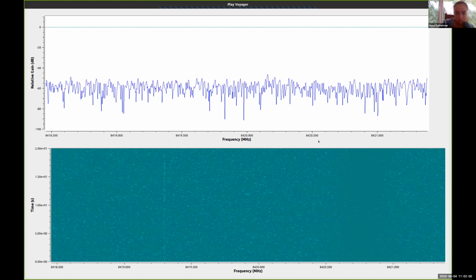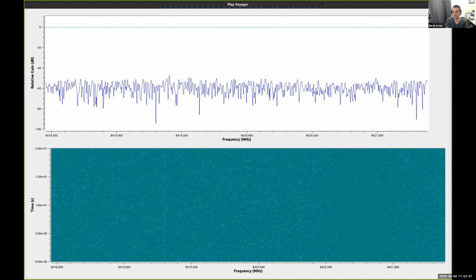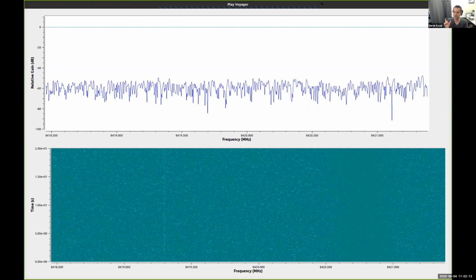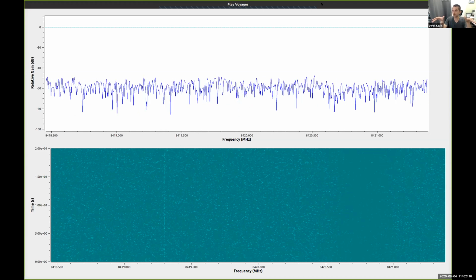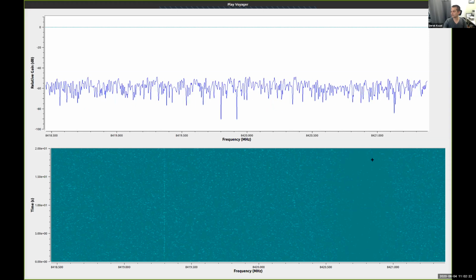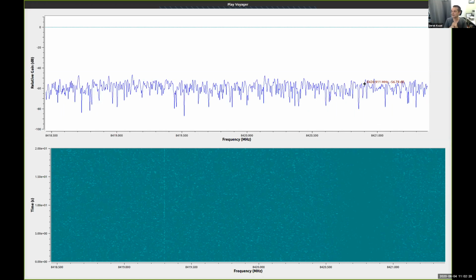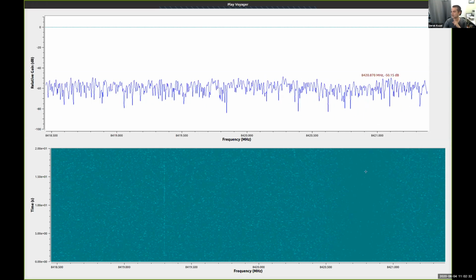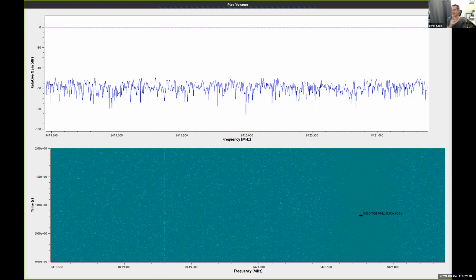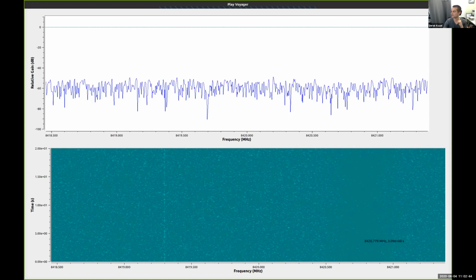So actually, okay, I'm going to take a guess at that. When you receive data using a radio, most of the time there'll be a bit of weakness at the edges. The signal level will drop on the outer edges of the band that you're receiving. One of the operations that I've done is to rotate the spectrum to fix a frequency error. And my guess is actually that the two edges have met here and have been rotated a bit. I've basically rotated it around the axis. I bet if I undid those, we would see that these are on either edge of the plot.